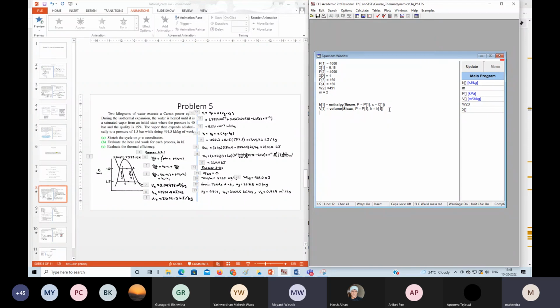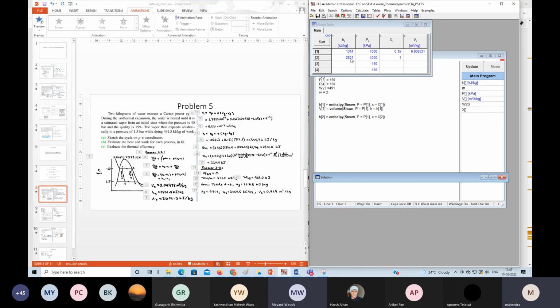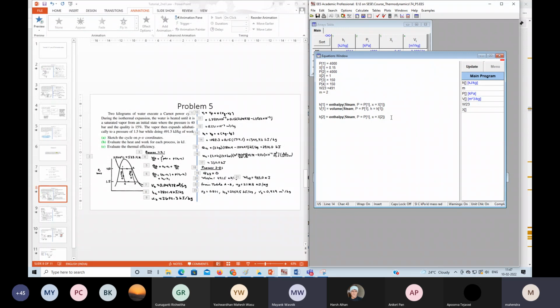Then like that, H equal to, I'm copying this. Here instead of X1, I'm giving X2. And then enthalpy. Enthalpy at 2 is 2810. Is it matching? Yeah, 2810 here. 2801, sorry, 2801.44. This is also 2801. Nice. Then let us get the temperature also.